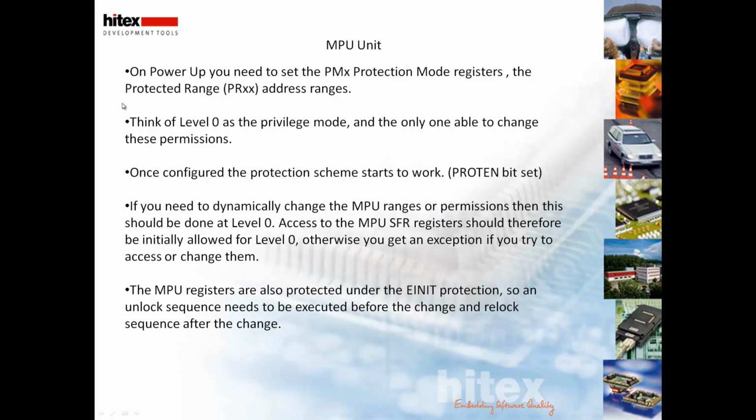Okay, to set up the memory protection unit, therefore, you have to set all the ranges up, and you have to set up the protection mode register. This has all the read and write permissions for the different levels. Think of level 0 as being the privilege mode, and the only one able to change these permissions. So that's the philosophy which you need to adopt within your memory protection unit.